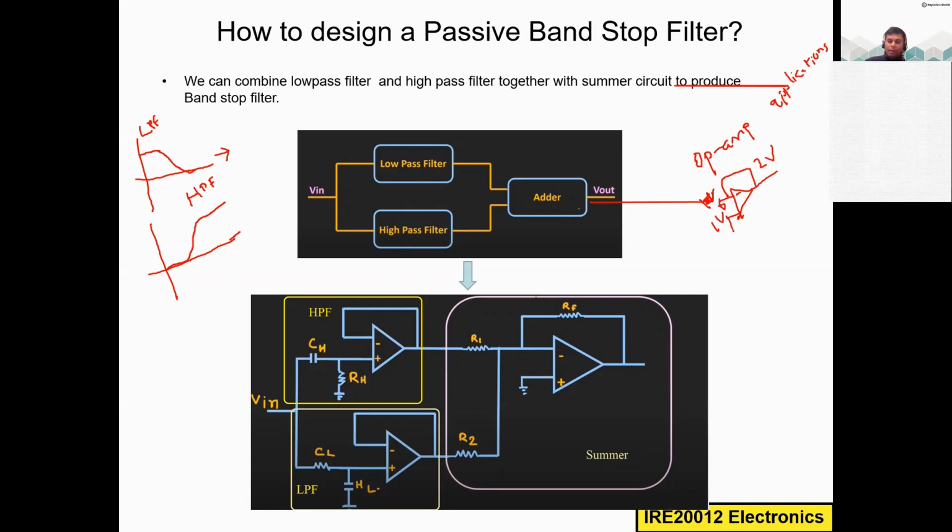And so here we will have multiple inputs at the other arm. So that is a positive side. Here we have more than a single input. For example, I can have 2 inputs, or 3 inputs, or 4 inputs. It really depends upon the application. So we can apply multiple inputs to the other input terminal of the operational amplifier, and then it will act as a summer circuit.